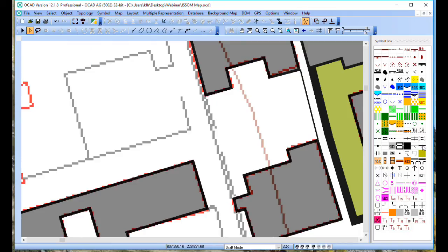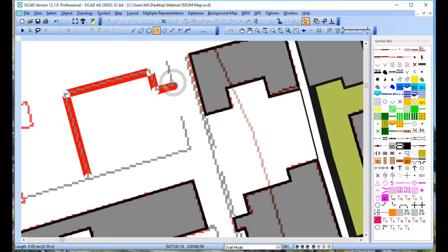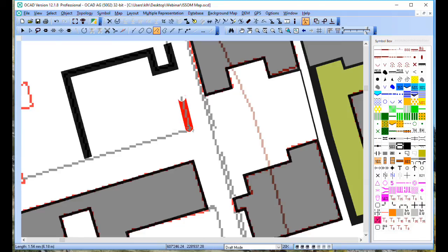For the walls and fences, I usually use maybe the rectangular line tool. It's the same as the rectangular mode, but it's for open geometries like lines here. If I have drawn the first line, then I don't have any angle. I just can choose the length of the next segment. So it's important here also to choose a longer edge for the first segment to make the angle as accurate as possible.